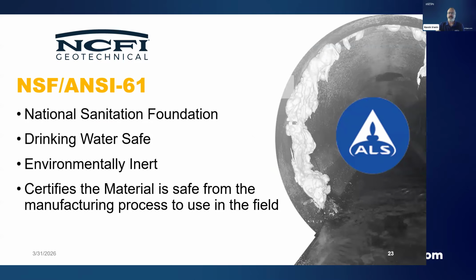We have available NSF ANSI 61 certification. So this is available, and it's by default on the NCFI 120, our single component systems. On our two component systems, at the current moment, it is by request only, but it is available. That means that if you have a customer that is concerned about water sources and that kind of thing, we can make the foam in a way that conforms to the NSF standard, ANSI 61.